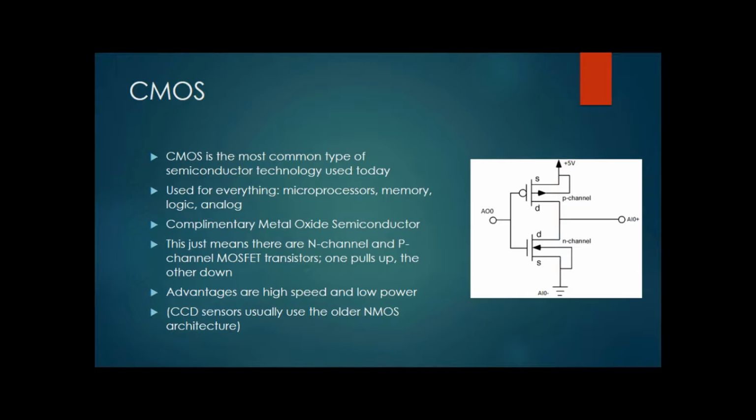The CMOS sensors are actually built using obsolete wafer fabs. And so, you know, when ON Semiconductor bought Kodak's wafer fabs, they kept them because that's what you need to build CCD sensors. They can't use the modern factories that are used to make memory chips and microprocessors. They're not compatible with the technology. So that's one of the weird things about CMOS. It's actually obsolete. Or sorry, CCD is actually an obsolete technology in many ways.